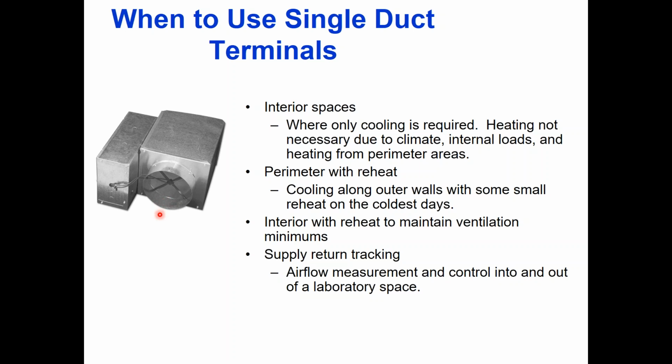But usually there'll be a few feet of flex duct coming in, and a lot of that is for sound reasons. Just like when you have diffusers, the last couple feet coming off the hard sheet metal will be flex duct going to the diffuser. That makes it so you can move the diffuser around to get access, and it also helps with sound.